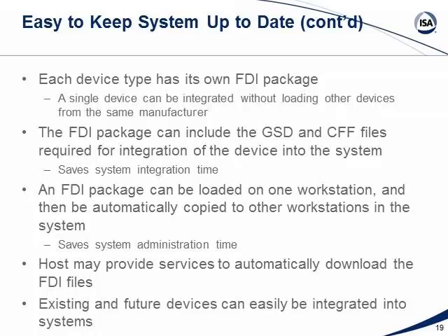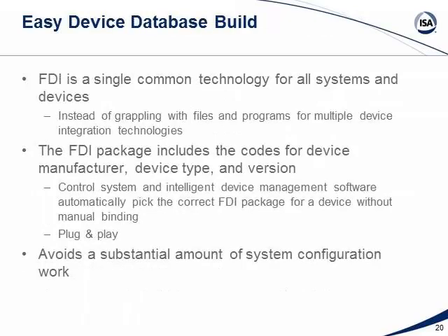An FDI package can be loaded on one workstation and then automatically copied to another workstation in the system. That means it saves system administration time. The host may provide services to automatically download the FDI files, and existing and future devices can easily be integrated into systems. The easy device database build. The FDI is a single common technology for all systems and devices instead of grappling, as I said before, with files and programs for multiple device integration technologies.